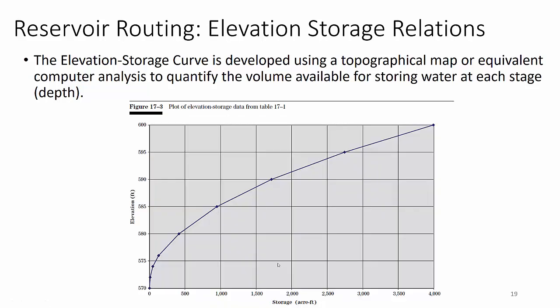And so it carries forward until you have a stage storage curve. And that stage storage curve looks like this. As elevation goes up, so does storage capacity. This should be starting to look familiar to you, because this is kind of what most of our curves look like. Stage discharge, stage storage. They tend to take on this parabolic look.